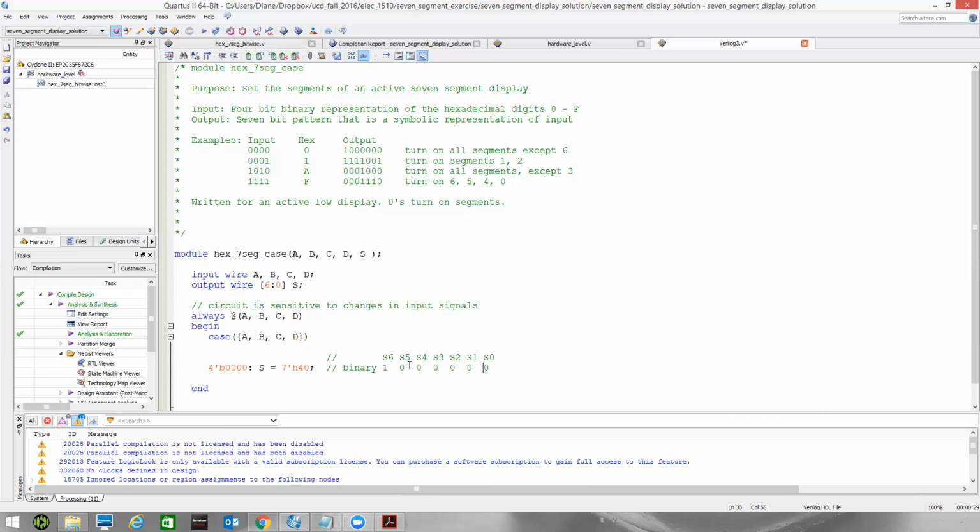So all we're doing really is typing that pattern. In other words, what we're going to do in the case statement here is type what looks like the truth table. These are our inputs, A, B, C, and D. That's the pattern that forms. And then there's the pattern our output forms. So we have the keyword case. We want to evaluate this as a 4-bit signal. We don't want to evaluate these individually, so we had to do the concatenation to say treat these as a 4-bit binary signal, form a number out of those 4 separate bits.